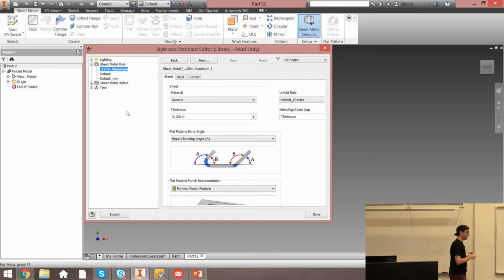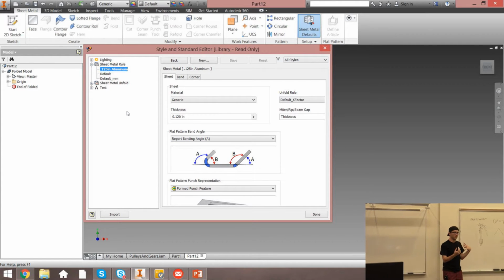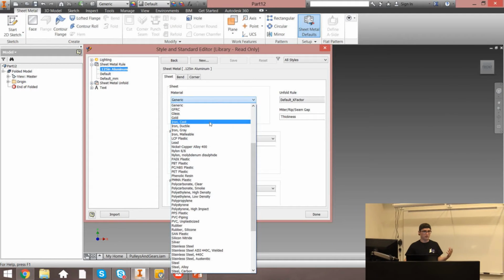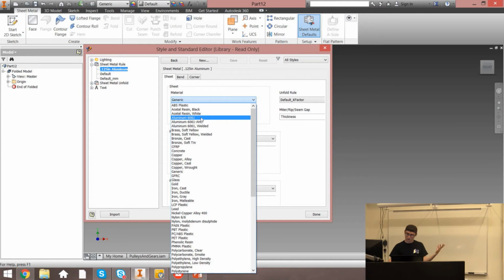Well, sheet metal defaults drive your entire system. If you click the face option, it's basically a quicker option of extrude. What that does is extrude to your default thickness. If your default thickness isn't the thickness you're actually using, then what are you getting out of this? So this accelerates that process entirely. Material depends on what you're using again: steel, aluminum, copper, whatever you're using.